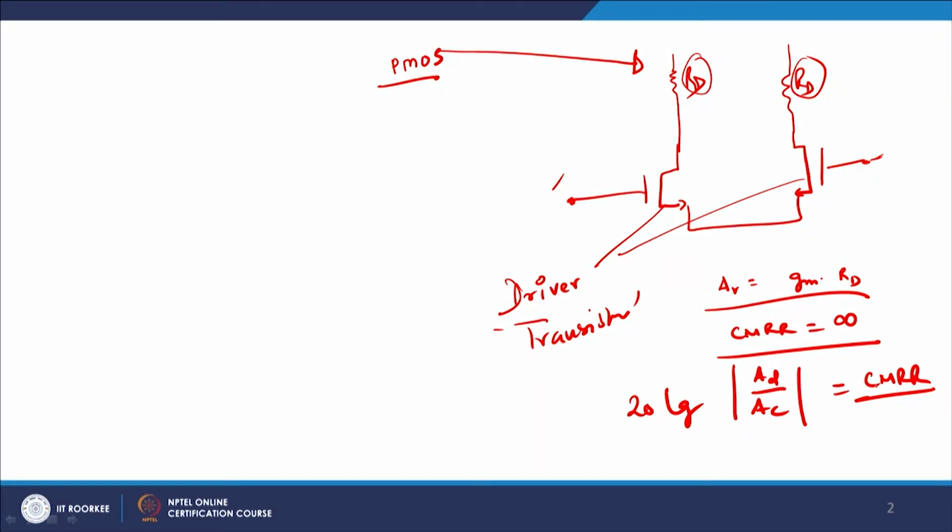What we will do today is look into the MOS differential amplifier part 2, where we will be replacing those RD, the drain resistances, by the typical PMOS. Before that, let me do one more amplifier design, and that is known as the MOS cascode design. Please understand, it is not cascade, it is cascode.